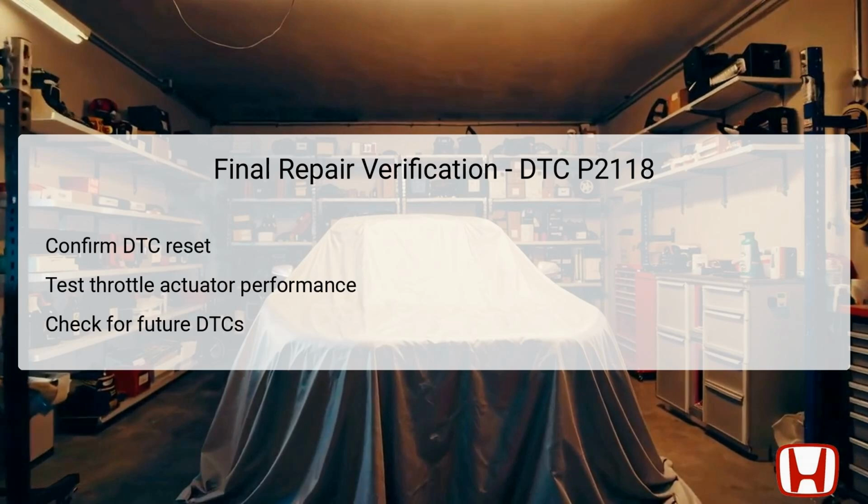functionality. A road test is also recommended to confirm that the vehicle operates normally without any throttle hesitation or power loss during acceleration. Finally, revisit the system once more to check for any future DTCs that may indicate lingering issues. This thorough verification process ensures successful resolution and provides assurance of the repair's efficacy.